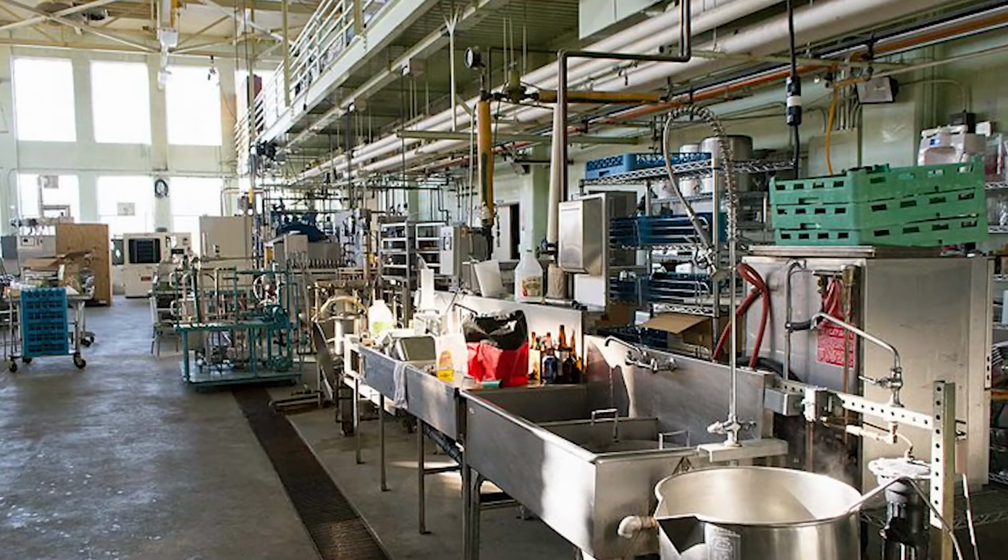If a facility has high BOD, suspended solids, fat, oil, and grease, or pH levels, they should take samples from the wastewater at the end of each process so it is clear which processes are contributing the most to the undesired levels in wastewater. Since not all processes are created equally, it is recommended that a facility start with adjusting the processes that have been found to contribute the most to the skewed levels in wastewater.